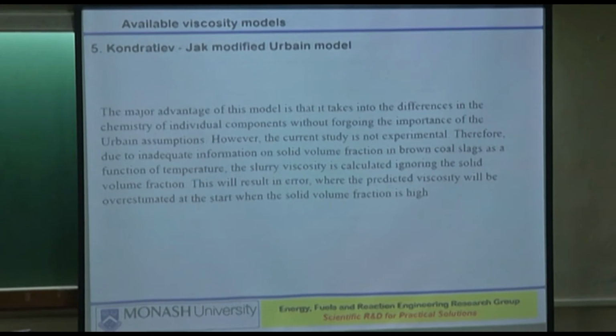If it is over melting point, good. How long I expect the slag to be at that melting point, I really need to know. If it is a long time, good; if it is a few seconds, okay, that will be a problem. Then solid fraction: maybe only the outer surface is a little bit molten, but the other bit is solid, so the solid fraction is very, very high. So these are some of the important considerations that you really need to know.